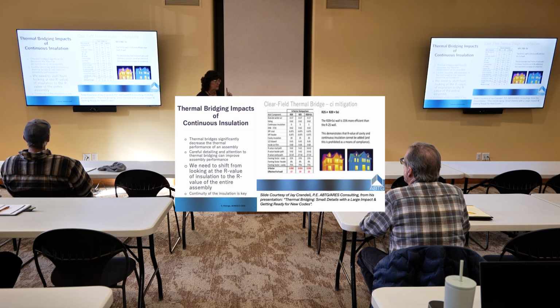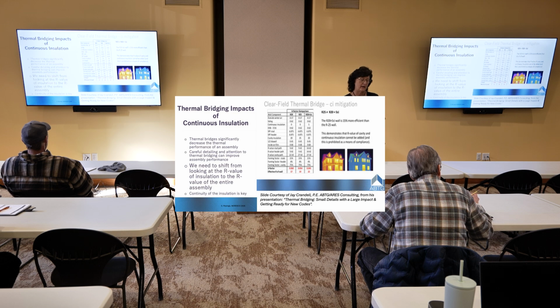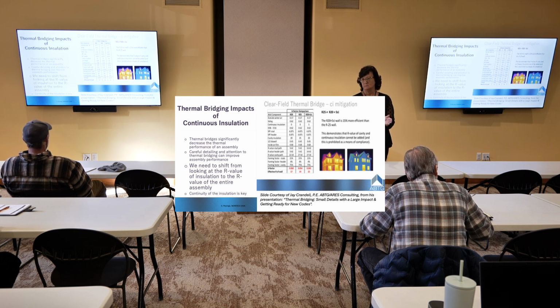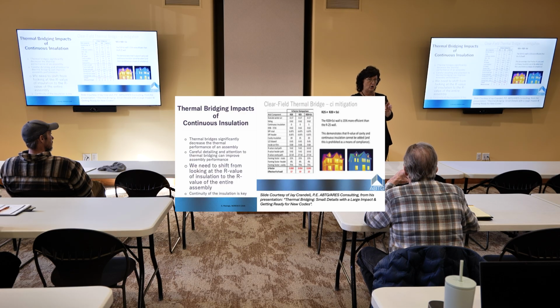This is what I want to talk to you about. I remember when I said, if I had that wall, and I put R20 on the inside, and I put R5 on the outside, but on the outside I use those Z strips, so now that's cavity and not continuous. That's an R25 wall, right? I can add up the layers because there's no air movement. So R20 plus 5 is R25 because they're both cavity. If I put R20 and I just use fasteners for the R5, now I have an R20 plus 5.